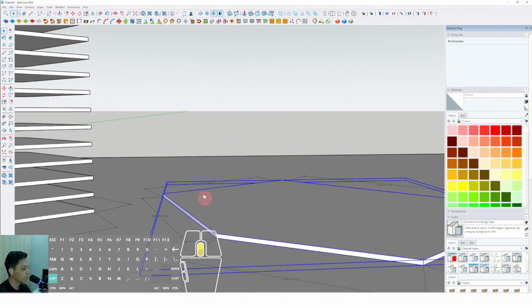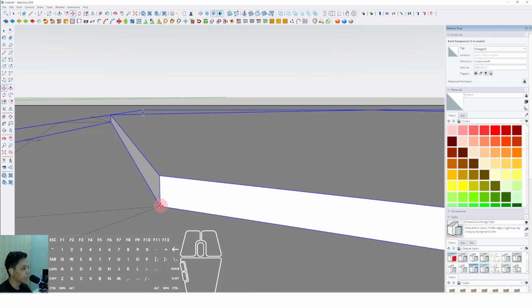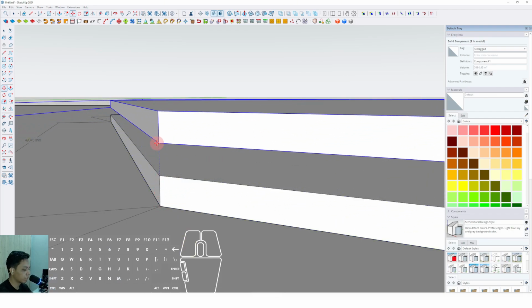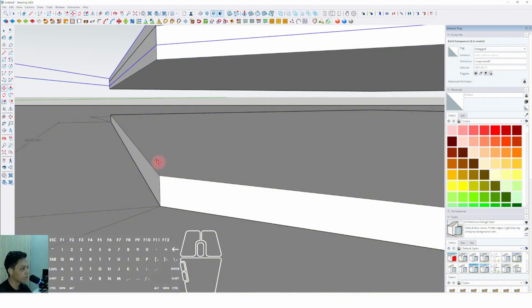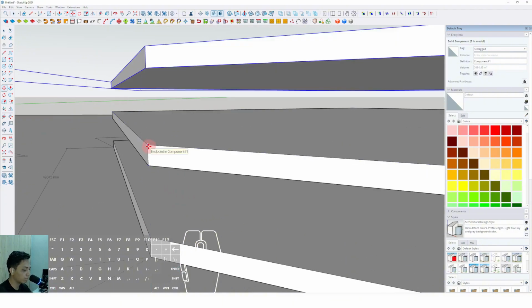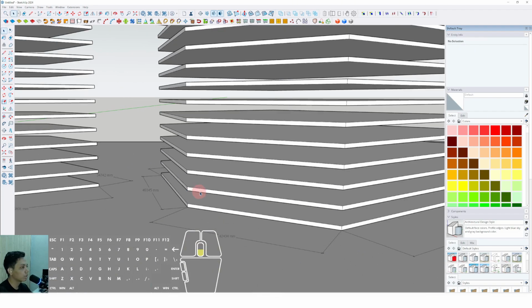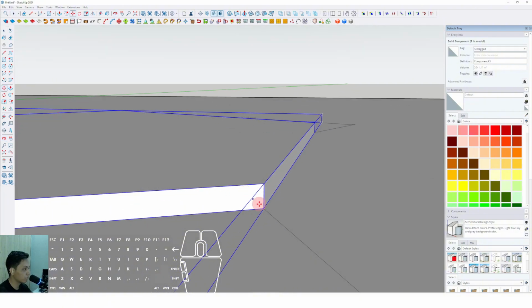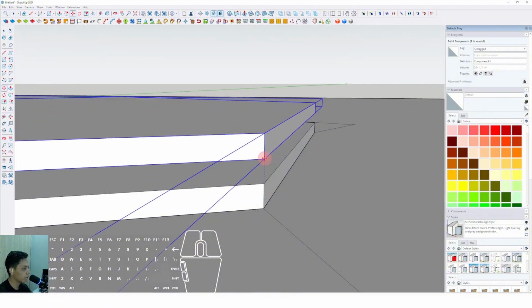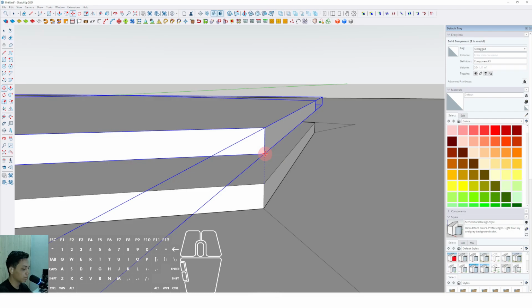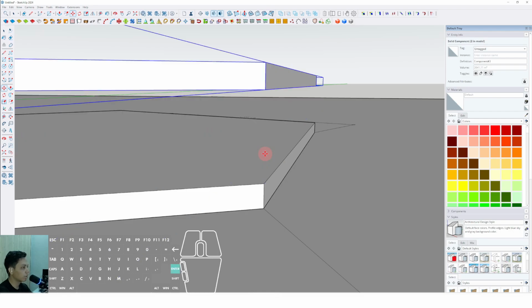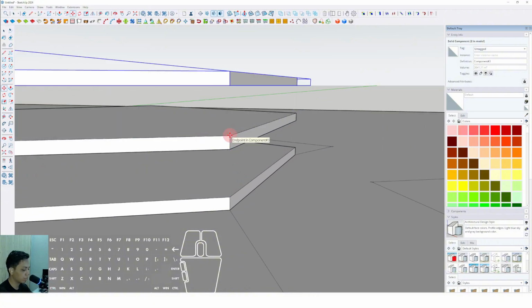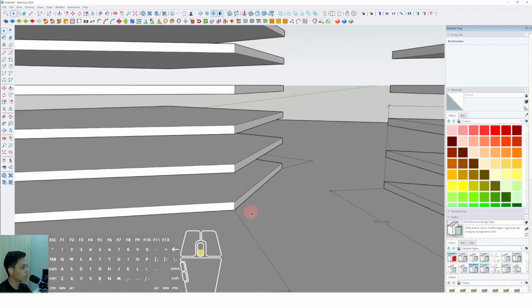And also this one, we select move, press Ctrl, place to this position, then type to move it up around 3.6 meters, enter, and then select move, press Ctrl, place to this position, then type X40 to duplicate it for the floors. And also this one, we select move, press Ctrl, and select move again, type 3.6 meters to set the floor to ceiling. Then we select move, duplicate above, and type X40 and enter.